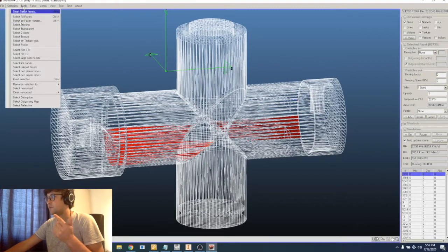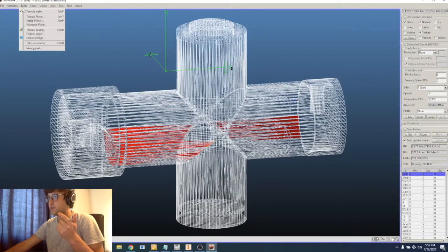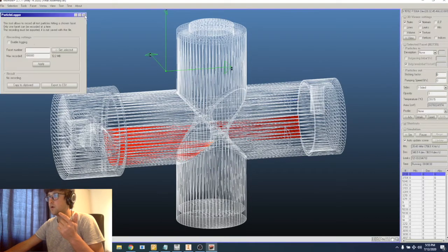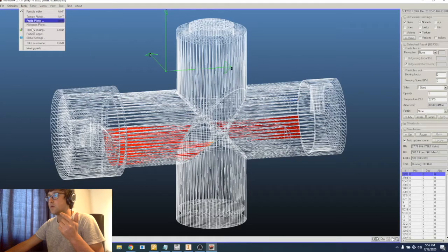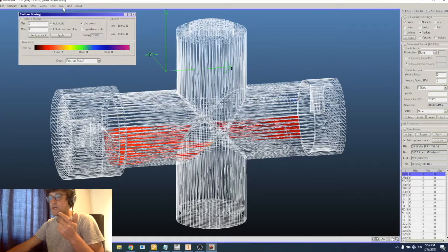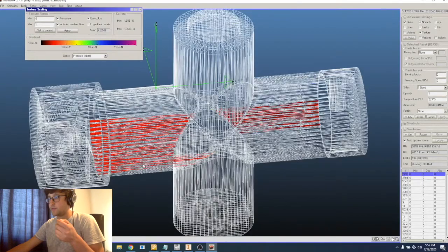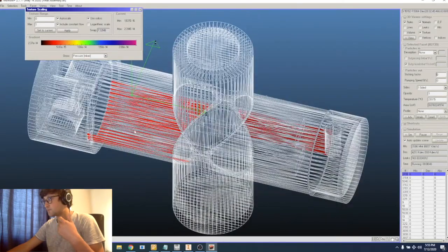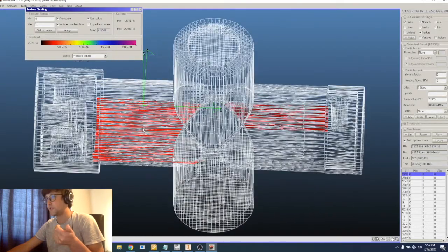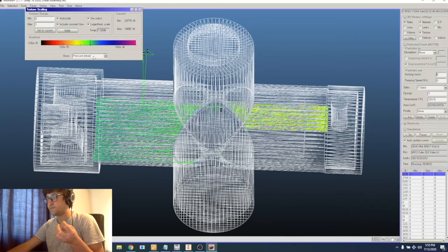So then once I have this stuff running, I want to actually look at the base pressure. I go to texture plotter. So you can export all the properties on these vertices also, but if I'm just running the simulation as is, I'll look at this. Usually I put logarithmic scale, and then I'll wait for it to converge.